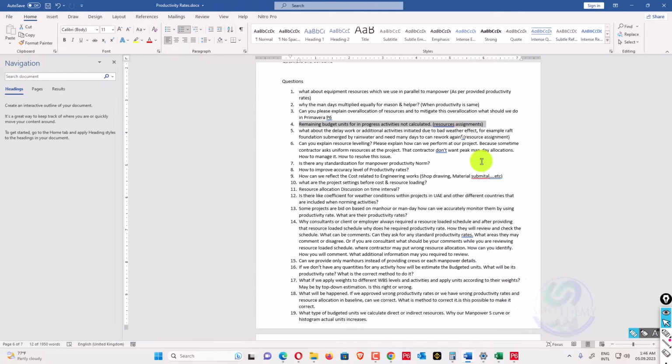So you have to design that project. You have to prepare the plan of the project in the form of a critical path, and that critical path is the basis. After that critical path, your resource is constrained. So with resource constraint, where your activity is appearing, you have to apply those resources. The contractor is always asking how to do resource leveling, please perform resource leveling. Maybe the consultant is asking to deploy this manpower, so he requires this manpower.